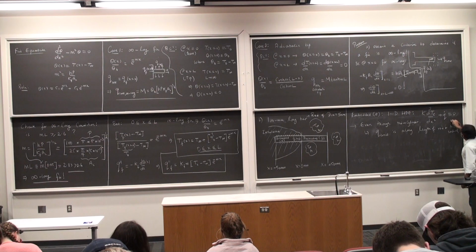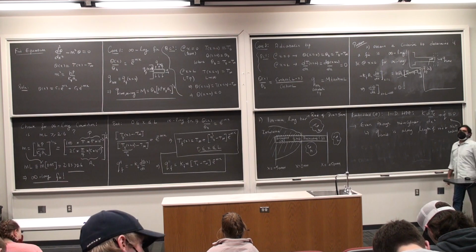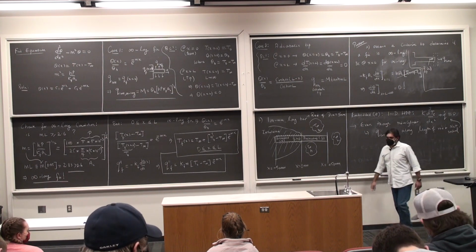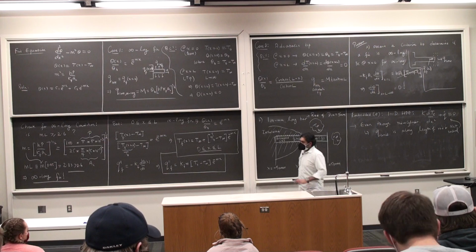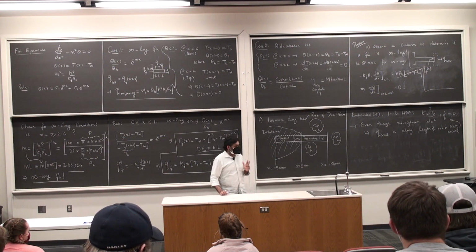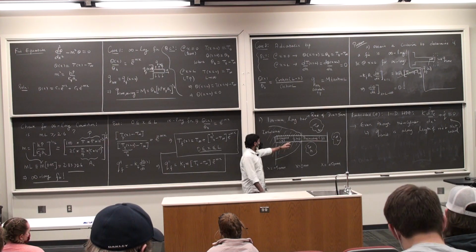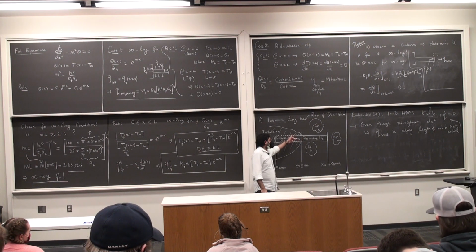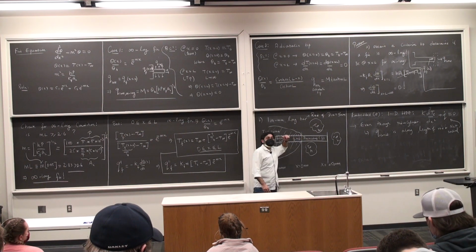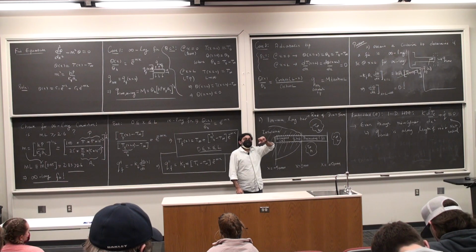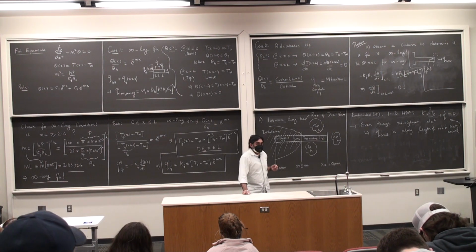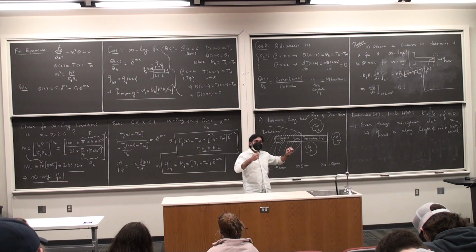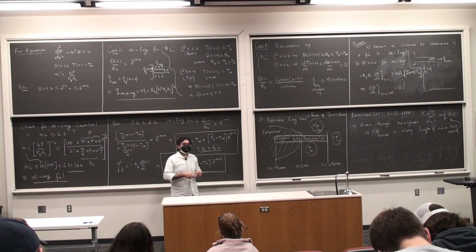And so we use the plane wall heat diffusion equation. Yes. If the top and bottom of the rod were not insulated, we would have to use a combination of the two, and it would make everything complicated. The direction of heat transfer would no longer be purely radial, so the heat going in here is going to be kind of tricky, right? The heat has to be transferring in the axial direction, which means that you will have to use a two-dimensional heat diffusion equation, where there is axial direction as well as radial heat transfer.